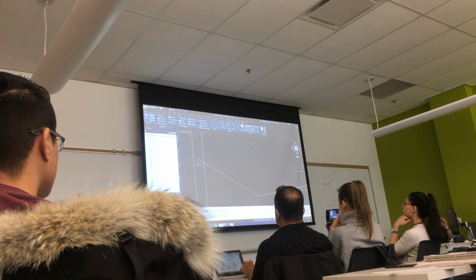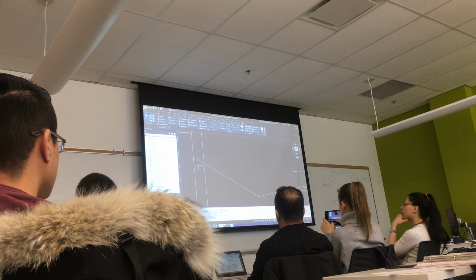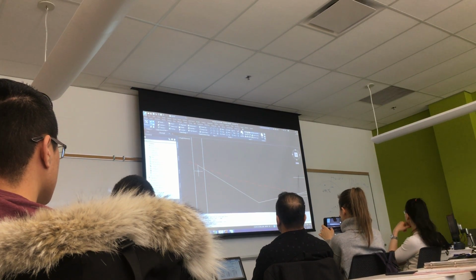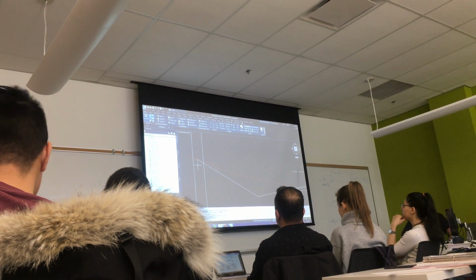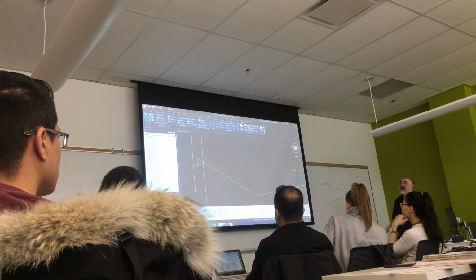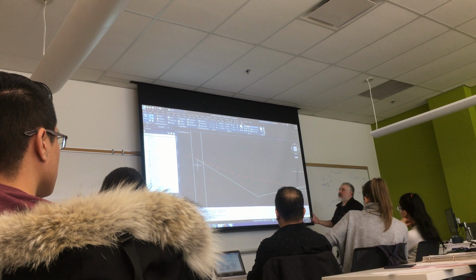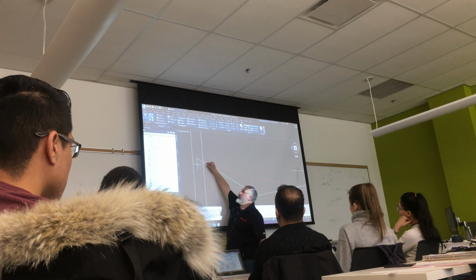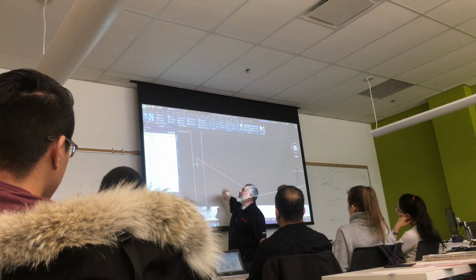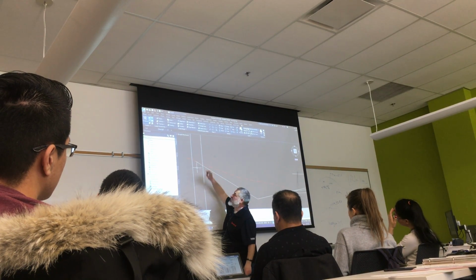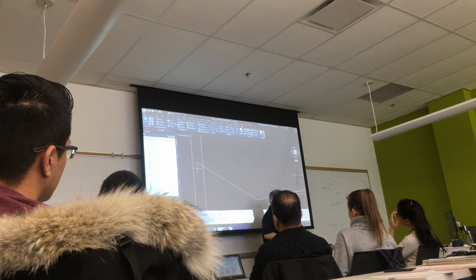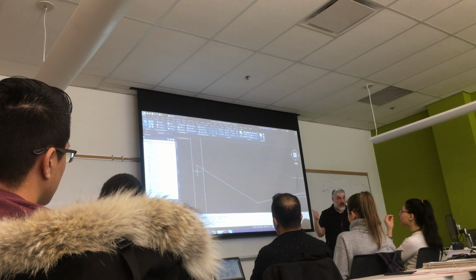Bit of a violation there. Everybody see that? All right? I'm supposed to touch the original ground, but within a meter of the edge of the actual right of way. So that's a bit of a violation. And this is the kind of stuff you're going to deal with. Okay? So what can you do now? Well, theoretically, you might put a little wall there, but it's not practical. This you might be able to get away with. Or if you draw from the invert to this intersection here, it's going to be a little steeper than 2:1. Okay? So strictly speaking, it doesn't work.